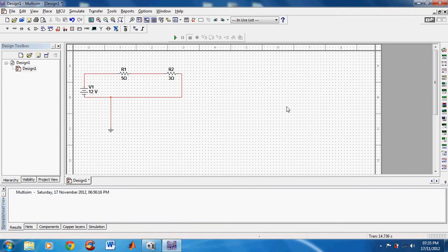readings. Now we're going to have to use a multimeter to test for those values. So at the side of your screen you are seeing a range of icons, and you're just hovering over them and you're seeing multimeter, function generator, wattmeter. We're going to select the icon that tells us multimeter. Click onto your working pad and connect in parallel to your resistor. That is to take your voltage reading for each resistor you're doing that. So click on the icon.